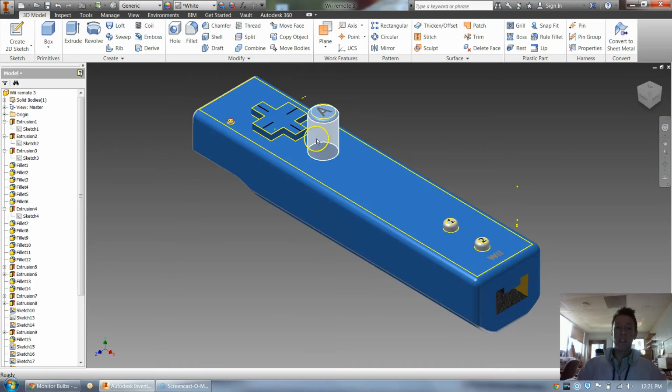So now let's say I want to fix this A button because that's obviously sticking out too far. And I just know from experience, like, hey, that's an extrusion. I must have extruded that too far, whereas the diameter of the circle is okay, but the extrusion is not. So what I can do is click these and figure out, okay, no, that's not it. That's for that bottom arc. That's for the lower buttons. The fillet, those are for the edges. Extrusion 4. Oh, extrusion 4, that's for the button because it highlighted it, so I know that.